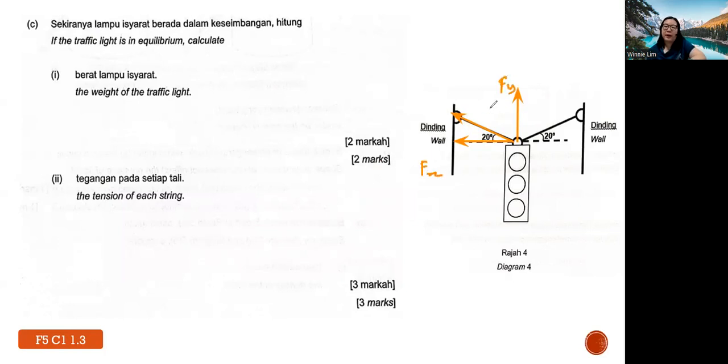And a simple idea I always tell students: you look at the angle touching the horizontal component, then this component is cos. So you will have T cos 20. Then the one not touching is automatically sine, T sine 20. You can rearrange into a right angle triangle and get the relationship through trigonometry. But the easiest way is to use this, because you always resolve a force with an angle. Then you will always have either sine or cos on one of the components.